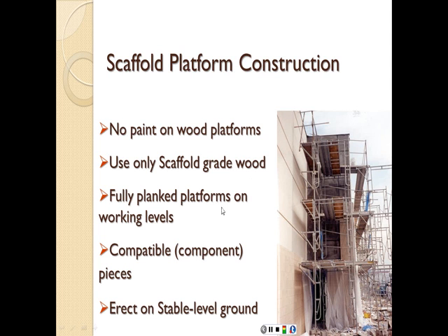Fully planked platforms on the working levels. This is a working level here. It seems to be properly planked, and so is this one. Compatible components or pieces, so by the same manufacturer or generic, but they can work together. And erection on stable level ground. So it doesn't show here at the bottom of the scaffold, but there should be some clearing and some good housekeeping to make sure that the footings or the foundations of the scaffold are on solid ground and at the same level to prevent differential settlement and shaking.